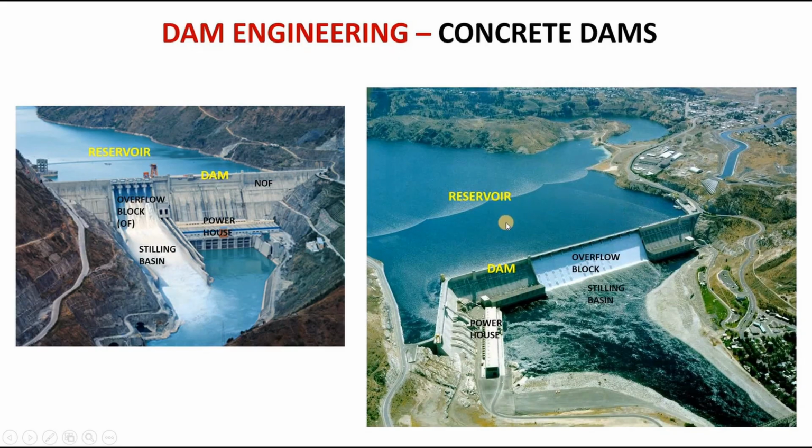We can appreciate here why at this place concrete dam is preferred over earthen dam. Because a spillway is a must and also to have space for the powerhouse, it is difficult to place the concrete spillway and concrete powerhouse in the space available. The width left after the concrete spillway and concrete powerhouse will be less, and placing an earthen dam along with its connection with the concrete dam will be difficult. Hence, for the above locations, concrete dams are preferred.